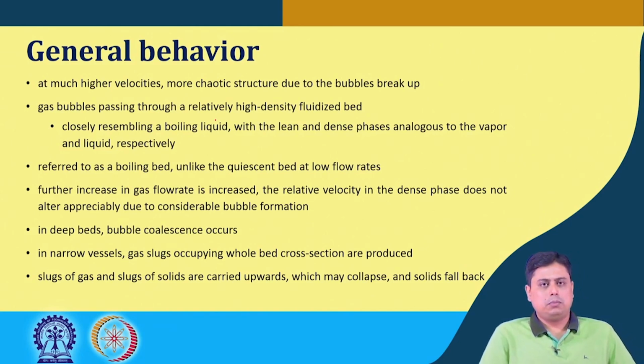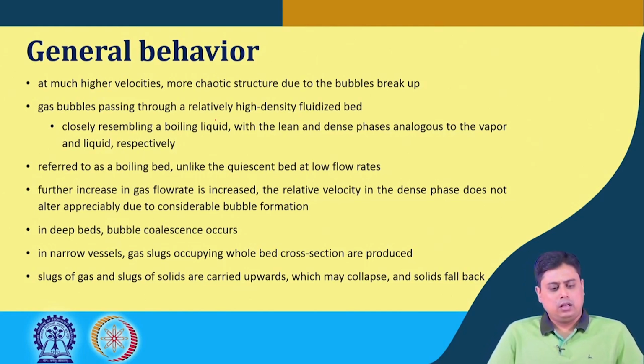So, the point being that at higher velocity we have bubbling phenomena in gas-solid fluidization, and this we typically refer to as a boiling bed, finding an analogy of boiling a pool of liquid and high flow rate through a bed of solid particles during fluidization. Okay.